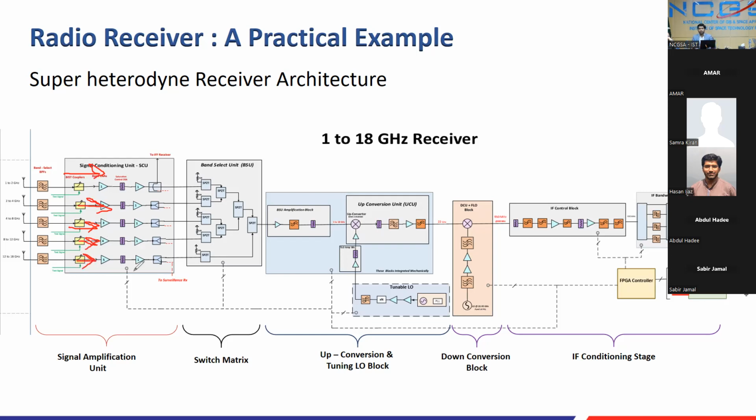The purpose of dividing them into octave bands is that for every signal you receive, you have a complete octave band. If any spurs arise, if any carrier arrives at 1 giga, its harmonic will fall at 2 giga, at the band edges. So you can regulate between band edges. So by dividing into octave bands, you can have a good noise figure configuration. We'll come to that later as well, how this helps.